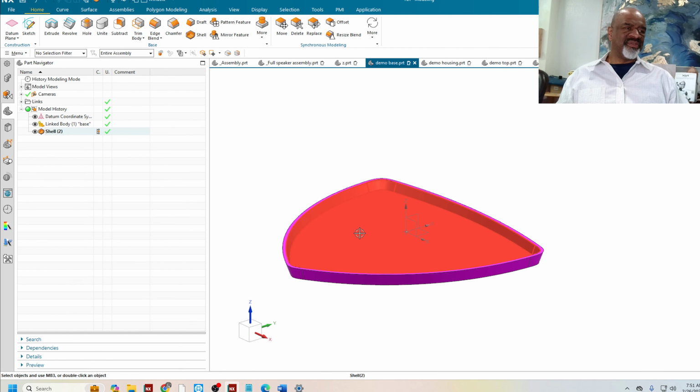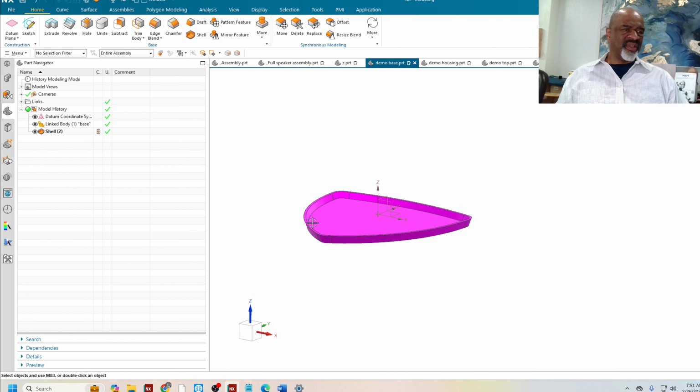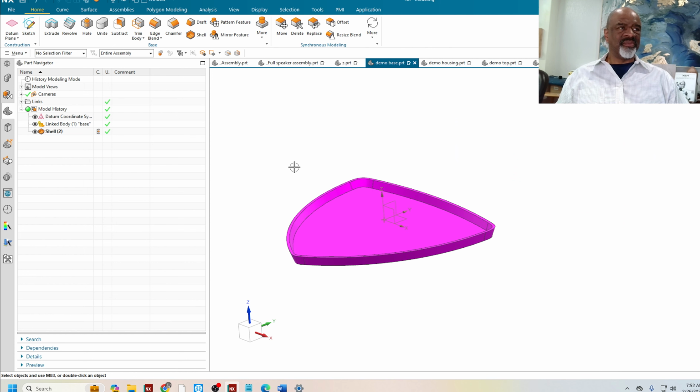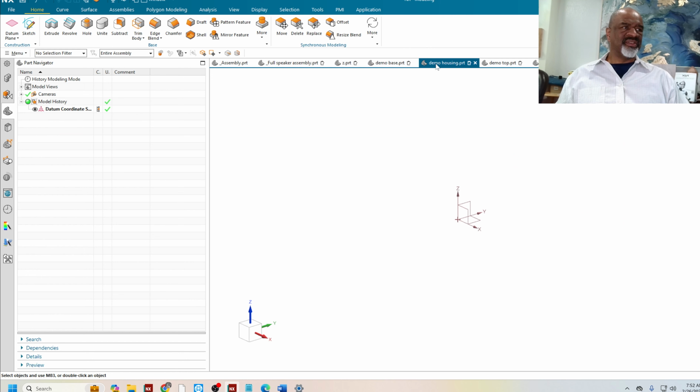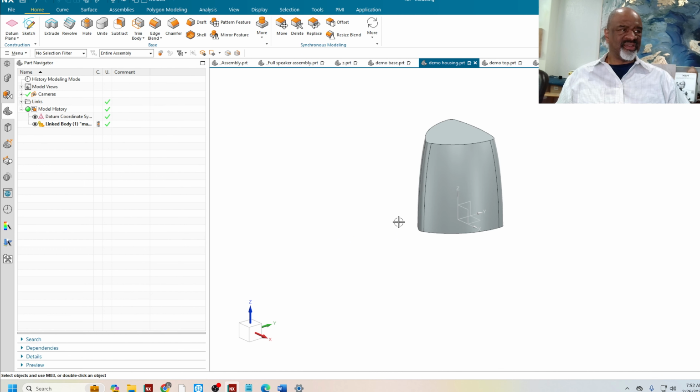Say okay. And it would have the screw bosses and the different goodies, and I would probably work a while on that and the reveal and how it interfaces with the housing. So anyway, let's go to demo housing. Let's do the same. File, more, wave interface linker. Pick up the part with all the interfaces on it. Go main housing. Say okay.